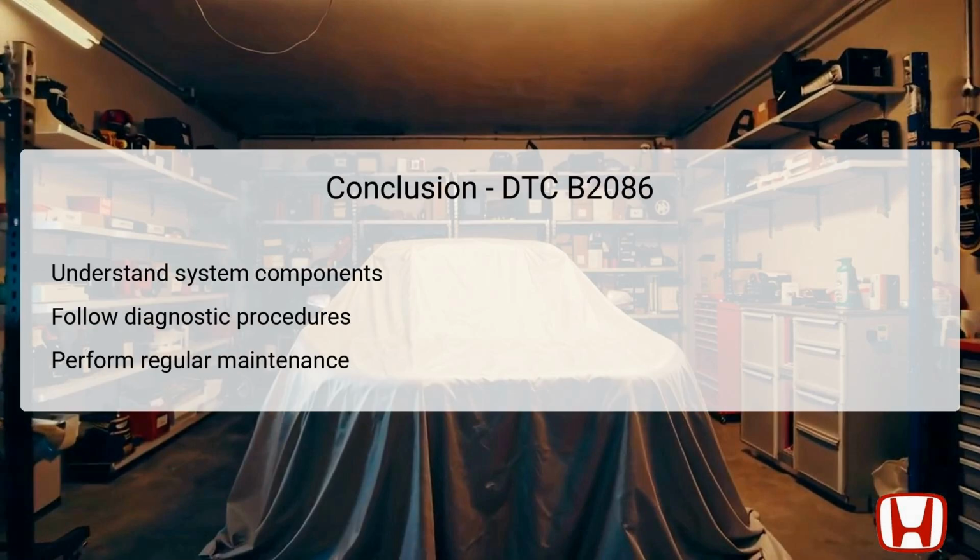In summary, understanding the complexities of the right power sliding door's electrical systems is crucial for effective repair and maintenance. Following the outlined diagnostic procedure systematically allows for accurate identification and resolution of issues related to DTC B2086.